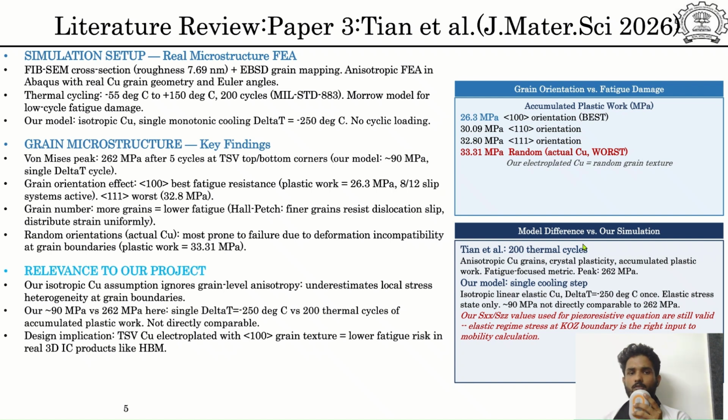Finally, relevant to our project, our model underestimates stress because it ignores grain level effects and uses isotropic copper. But our stress values are still valid for mobility calculation. So overall, this paper shows that grain structure and orientation play a critical role in the reliability of TSVs.